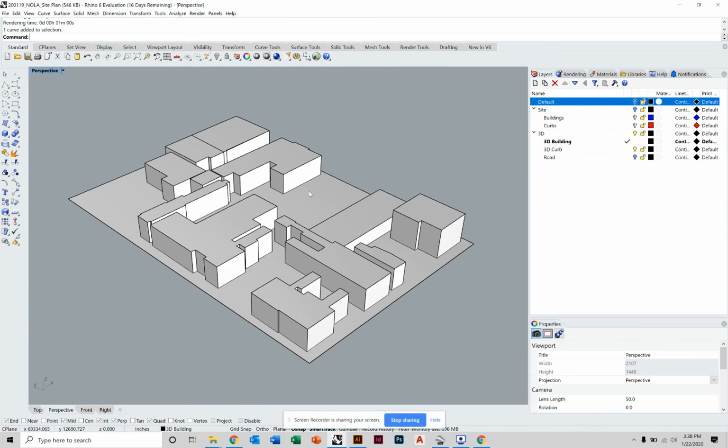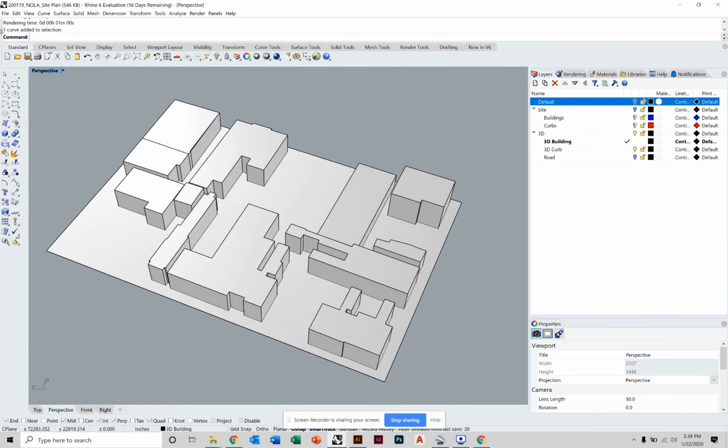Yeah, you guys can start using this too. If you want to start getting to work on your projects, you can start generating or preparing your files so that you can start generating site plans. And since we have a 3D, we'll actually be able to cut a section through this and get sectional information. I just wouldn't do that yet because we're going to cover accurate heights for the buildings next week.